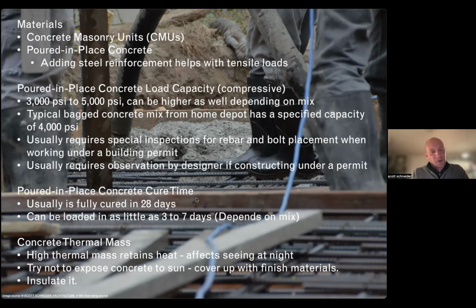Getting back to concrete, I think I left off at the bearing capacity of concrete. So moving on to the cure time: after you pour it, concrete is normally almost at its full bearing capacity in 3 to 7 days, but it fully cures in 28 days. So usually in 3 to 7 days, you can start putting framing on top of your concrete.